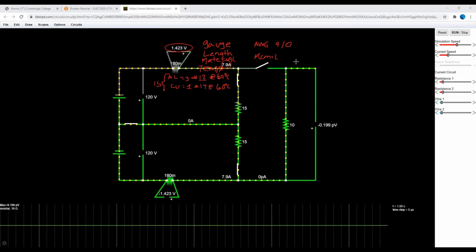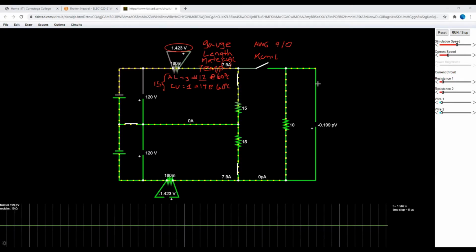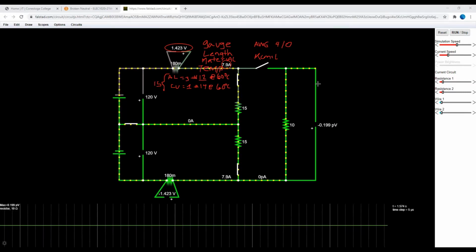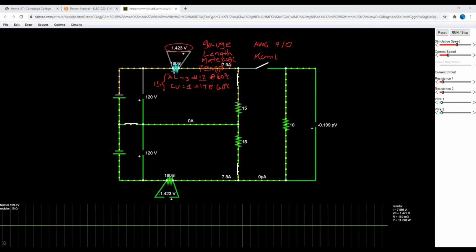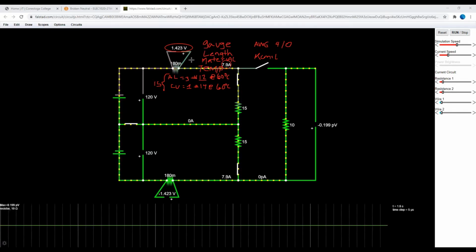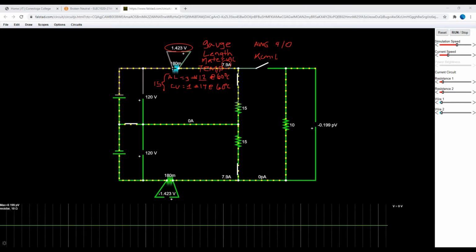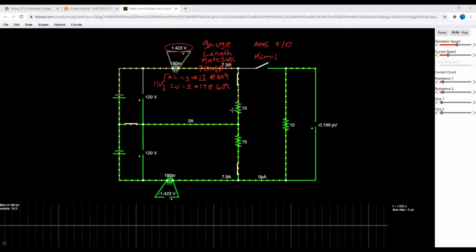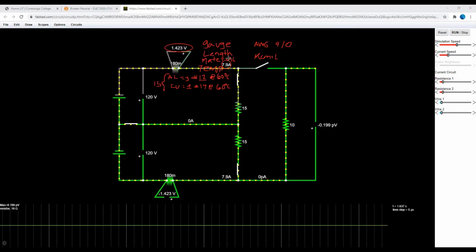Okay, guys, so you could take a look at the circuit and start thinking about how any of these values are going to be affected. The voltage drop that you have on the conductor is also going to be affecting your load. And that's why you have to derate the conductors because of all these different issues.